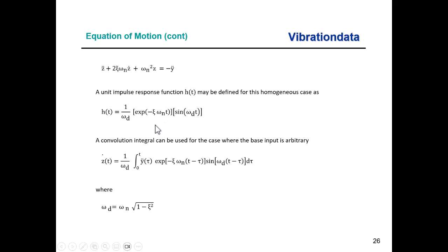So what this really is, if we give a velocity impulse to the system, what will its resulting displacement be? In order to carry out the full solution to get the relative displacement, we have to use something called a convolution integral. You may have heard it referred to as Duhamel's integral. We're going to take this unit impulse response function and embed it. Now, we're doing something kind of funny with the time, because we've got this tau variable here, which is a pseudo time. We impose a kind of delay function, so time changes to, in parentheses, time minus tau. You see that both for the exponential decay and the sine function.